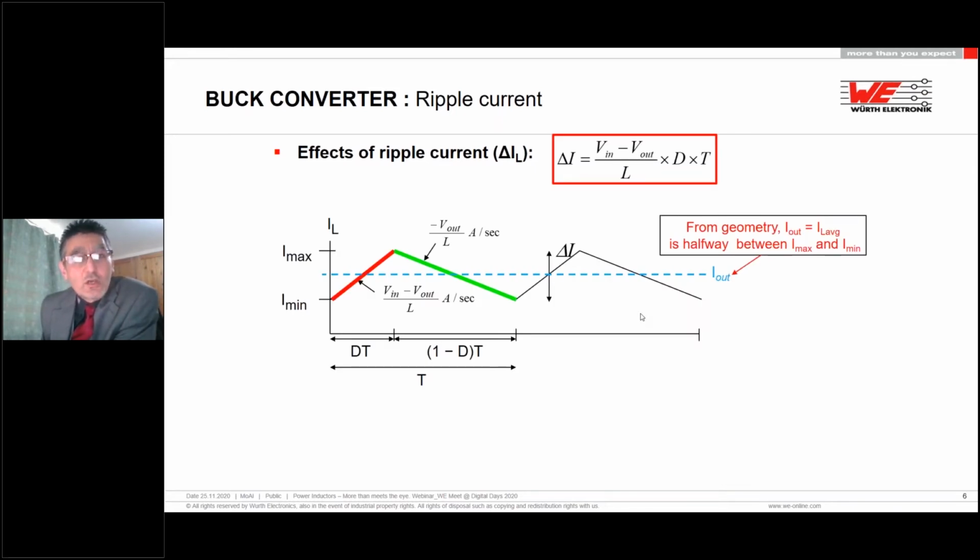And the following few slides are just showing a representation of some of these waveforms, and we're going to concentrate, in this presentation, on the inductor ripple current. In the next one after this one, we'll talk about the capacitor side of things, but for now, let's talk about this delta IL, which is the change in ripple current, as a function of a few parameters, which we will come to over the next few slides, but it is the key parameter when it comes to selecting the inductor. It is in a way also your degree of freedom. This is your flexibility to select a value for this ripple, and we will see this in a bit. Why is this so important? It impacts something called CCM or DCM, operating in continuous or discontinuous conduction mode.